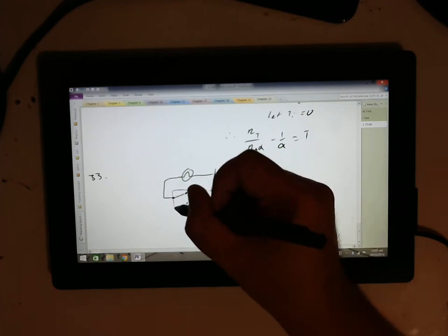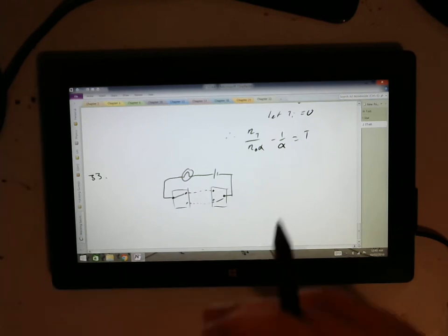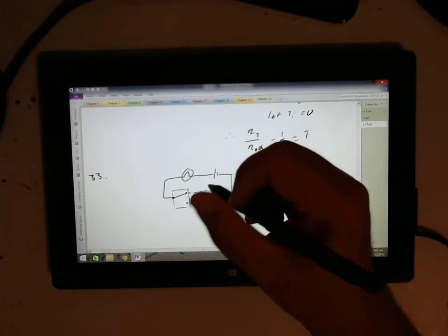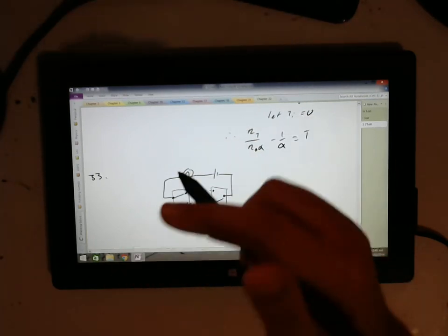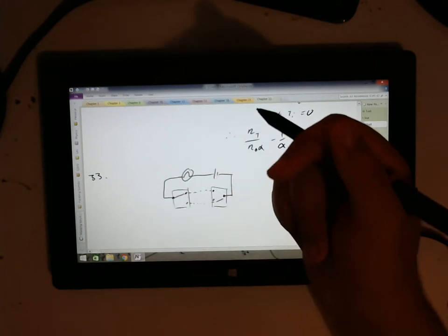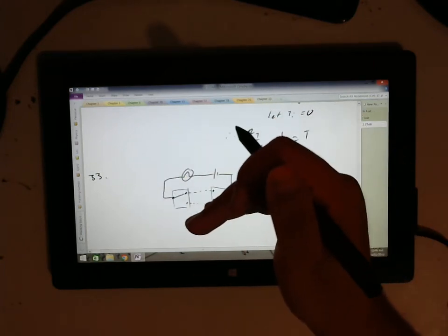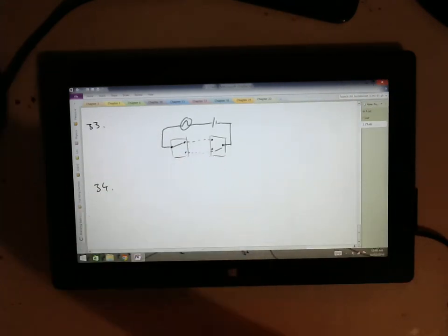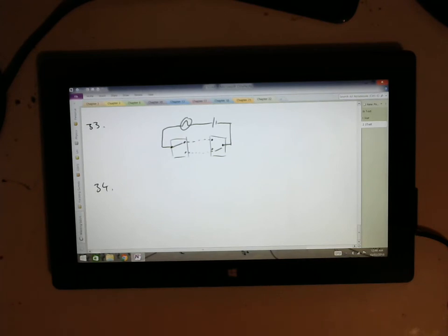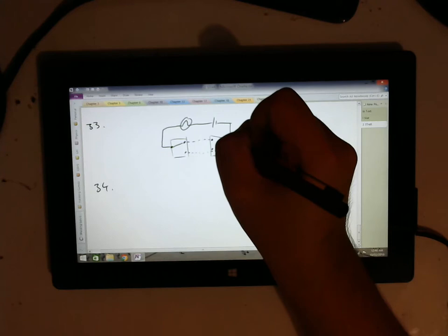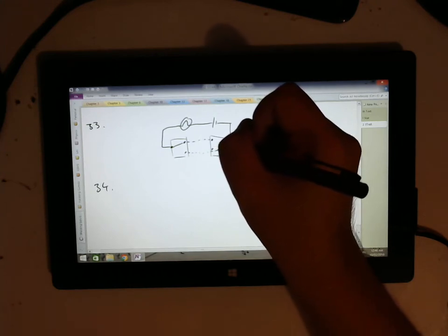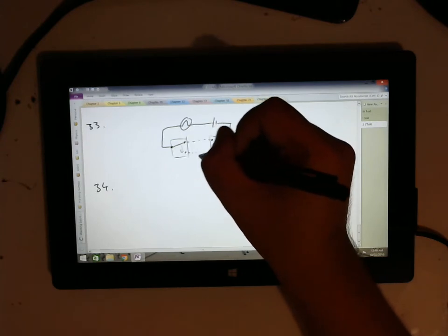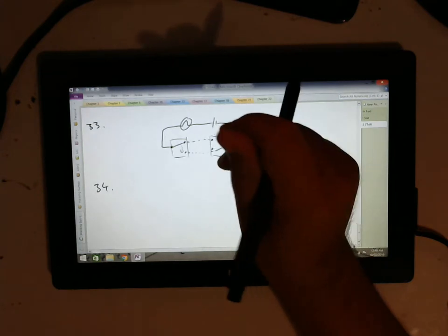And while I know the circuit diagram for this doesn't exist in your textbook anywhere, these sorts of things are worthwhile looking up because you can find a whole bunch of examples. But that's how we do a two point switch, where they're both in one position. We've got current, you switch one to the off, they both break, it stops because the current can't flow through. Both of them need to be in the on position. And the good news is that if I go, it's bright and I don't need to turn it on, and I go up the other end, and later in the afternoon coming back it's dark, I can just switch this to the other side, and even though it was in the off position, now it's been put into the on position.